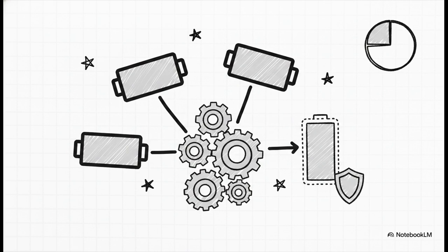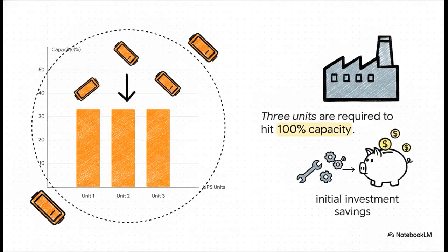For example, if your facility has a massive load of 3,000 kilowatts, you don't go out and buy 3 gigantic 1,500 kilowatt machines. Instead, you install 4 1,000 kilowatt units. You still have that vital +1 safety net, but you've essentially sliced the pie into more pieces.